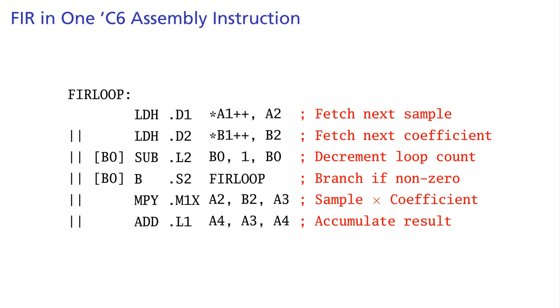Its basic failing is its insistence on a single program counter. It turns out to be very difficult for a compiler to find and exploit the kind of instruction-level parallelism required by a VLIW architecture, even for signal processing applications which tend to have simple control flow. Processor architects have instead built processors that attempt to derive such instruction-level parallelism dynamically, sometimes even from multiple instruction streams via simultaneous multithreading. But the path of least resistance has turned out to be multi-core processors, which provide a more traditional multi-threaded form of parallelism at the expense of shared memory coherency issues.